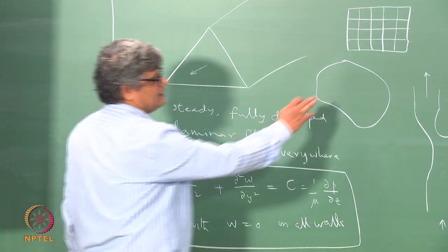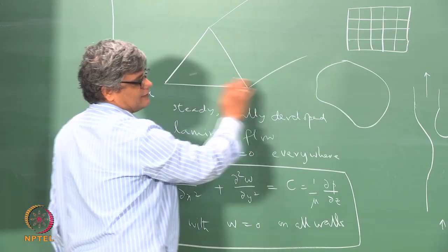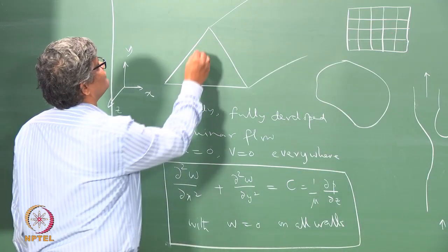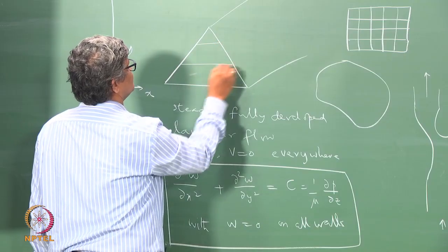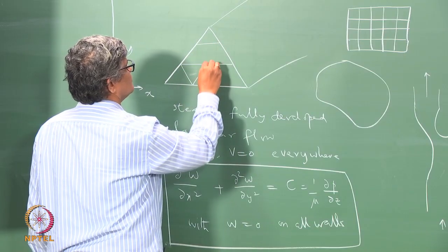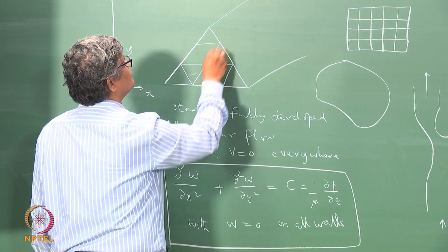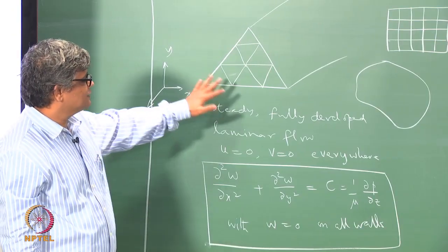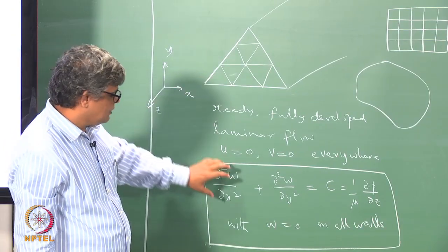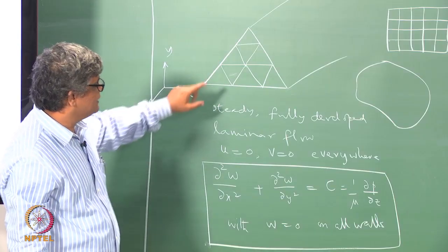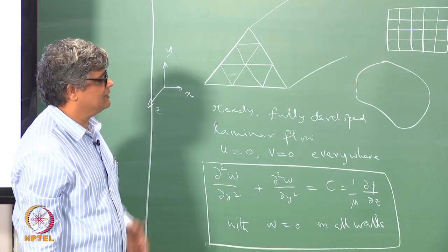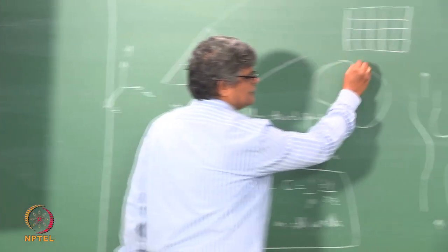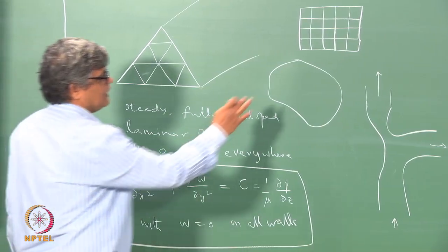So the basic idea is not to be restricted to have these kind of rectangular cells making up this, but we can have cells like this. We can have triangular cells, okay, and these triangular cells, we would like to then solve this equation around this, and this kind of triangular cells can easily enable us to deal with even a geometry like this.